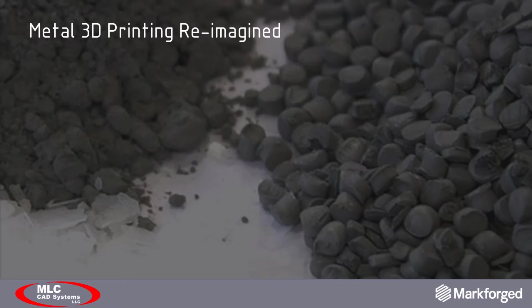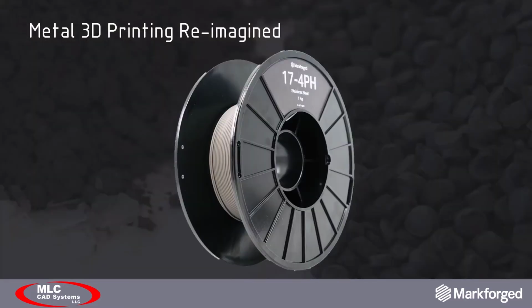Essentially, a raw metal powder is combined with a wax and a polymer, which is then extruded into a filament. If you're familiar with 3D printing, this is very similar to a traditional FDM style process. The process yields a raw material, which we call a filament, which essentially encapsulates the metal powder, which otherwise requires significant precautions. These spools are easy to handle and easy to store, which was a big thing for Acme Audio. They couldn't really take on any manufacturing processes that were going to be overwhelming to their design process. Like most customers, they run a very lean operation, and they needed their manufacturing processes to be lean also.